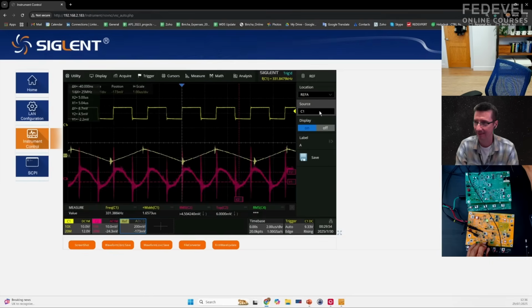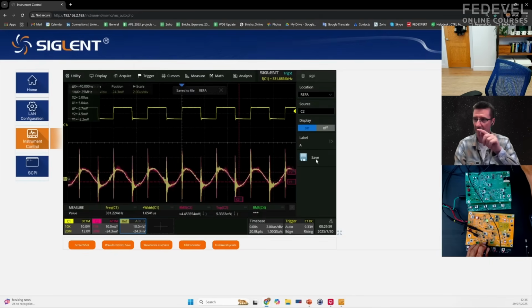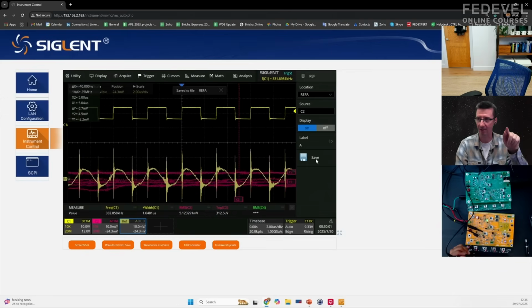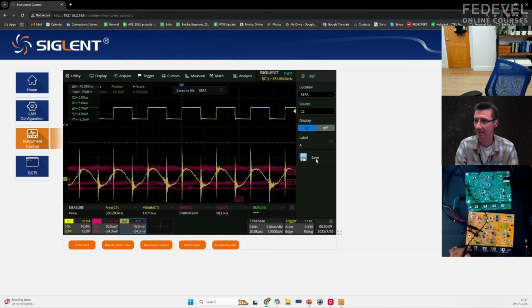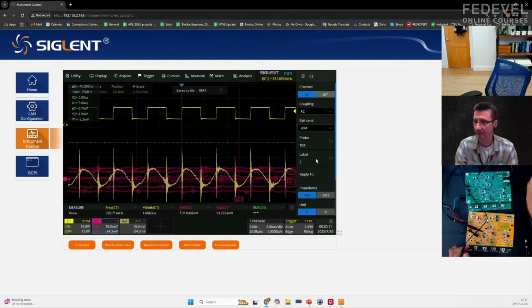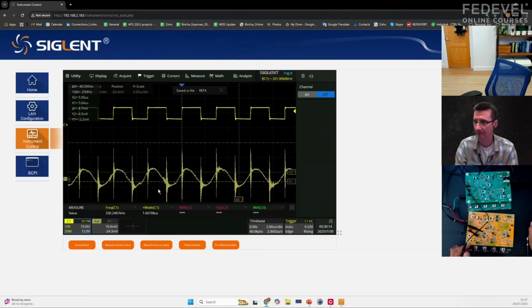Yeah, we can actually see how the capacitor is discharging and charging, discharging and charging. Yes, that's exactly what is happening. And remember that the inductor current was a ramp, right? So turn that off. So you can see that it's not exactly sinusoidal. Can you see it's kind of a ramp up here and is ramping down? Yeah. Right? And that is because the inductor current is a perfect ramp and it's being integrated by the capacitor,